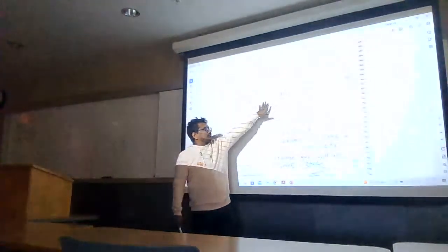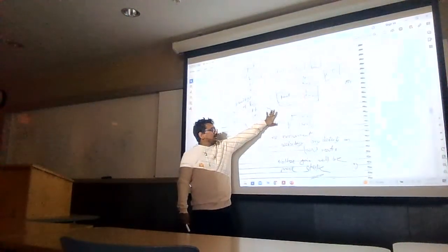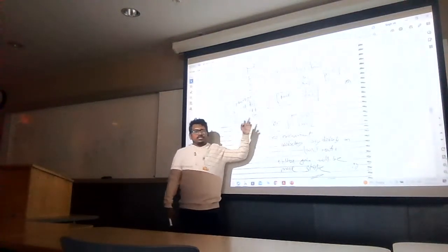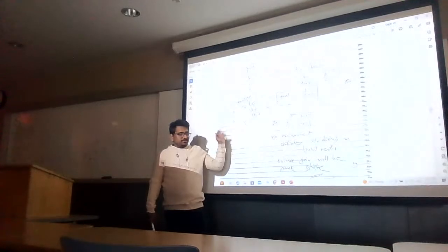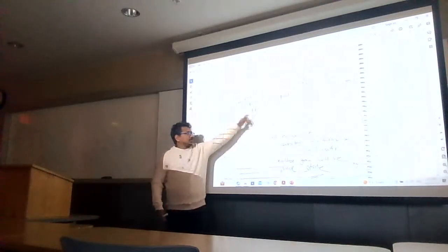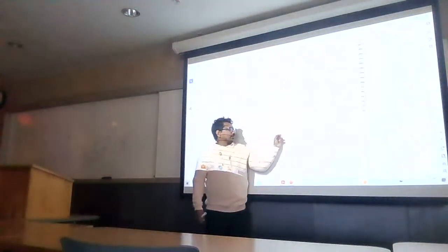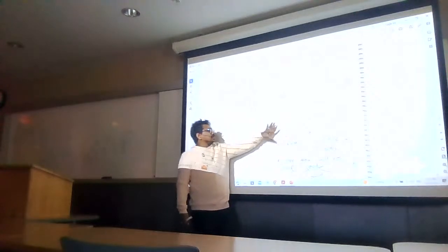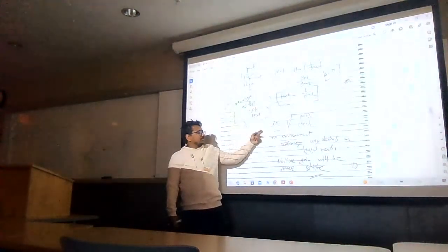If you put one of these formulas here, there are some constants, mu and Cox, W by L something. So mu and Cox are constants, they will cancel from top and bottom, and only the W by L of each is left.